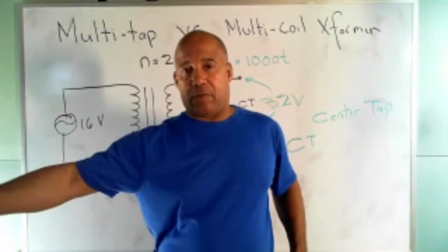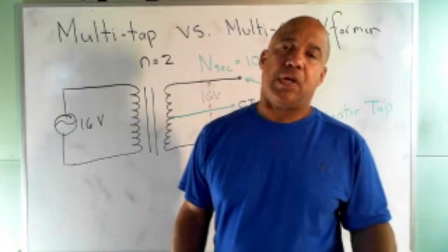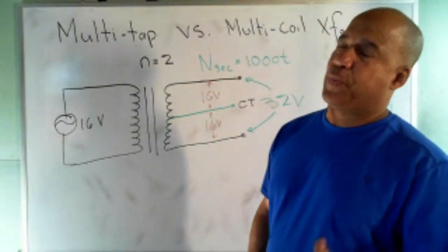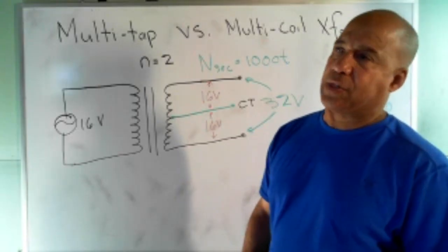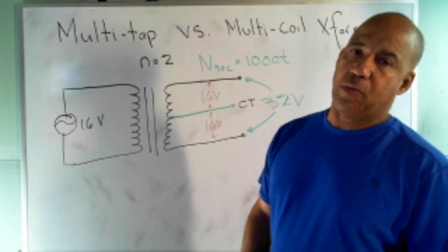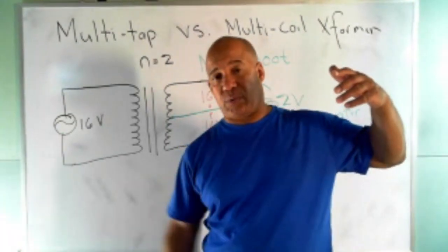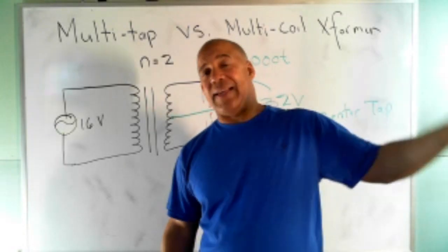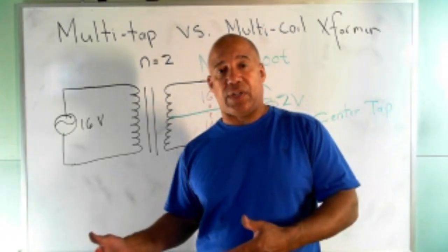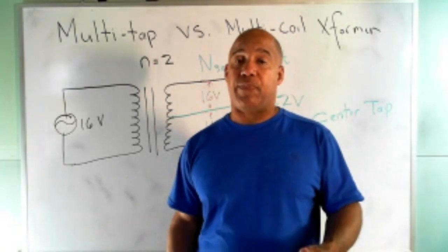What happens is when you plug your computer into the wall, you've got 120 volts. Well, most of the circuit boards in the computer are way less than 120. We probably have some 5-volt boards, and I wouldn't be surprised to see some 12-volt boards. You won't have a 120-volt board. So you have to do 2 things. You have to take the 120 volts from the wall outlet and step it down to something closer to the actual DC voltage that the computer needs, and make sure you realize that it is DC, even though you plug it into the wall.